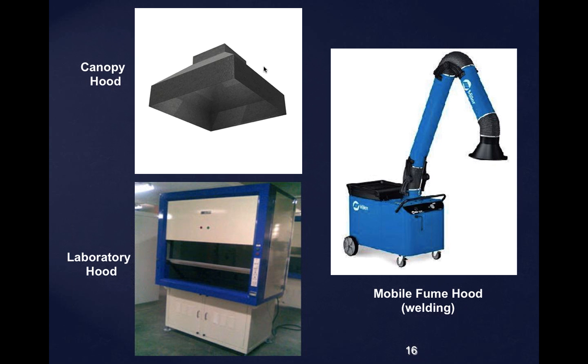In air conditioning systems, we don't see blast gates. What do we see in an air conditioning system instead of a blast gate? Instead of this thing that just dropped. The only thing you'll see that looks like a blast gate is something called a fire damper. A lot of times in air conditioning ductwork, they will have a damper, a blast gate, that's hung up and held with a fusible plug, a little piece of metal that melts at a low temperature.